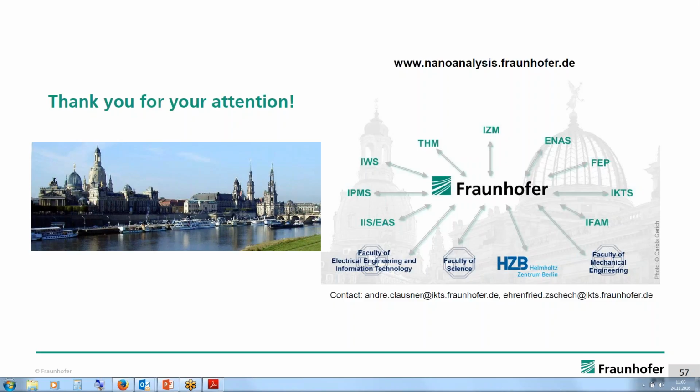And you have access in the chamber also, if you mount it, to EDX, so chemical composition measurement, you can check around the area what chemical composition it has, or you have also EBSD, so crystallographic orientation. What we do a lot is in situ in the SEM, we put the sample there, we make an EBSD map, so we check the single grains and which crystallographic orientation they have, and then we make a mechanical experiment at one particular grain with the orientation that we want, and then we can have a look after the experiment and see if the grain is rotating and what happens.